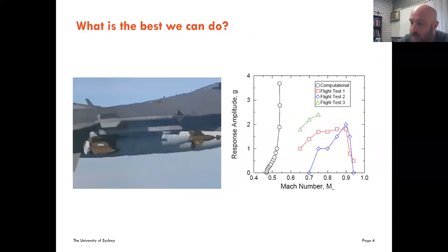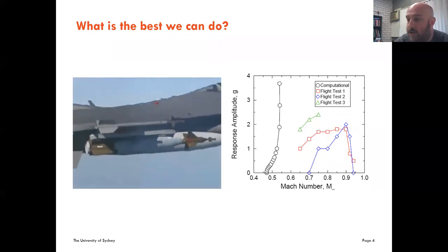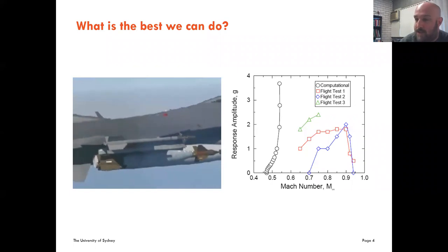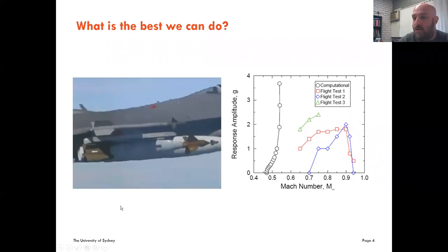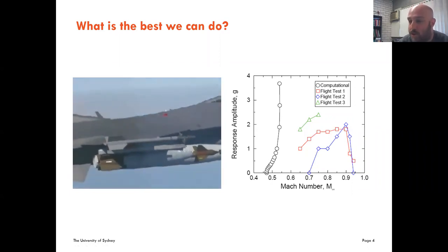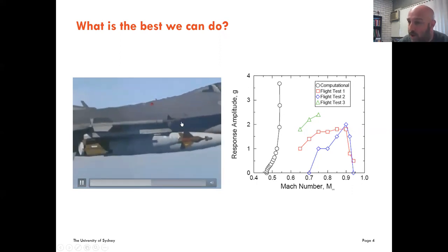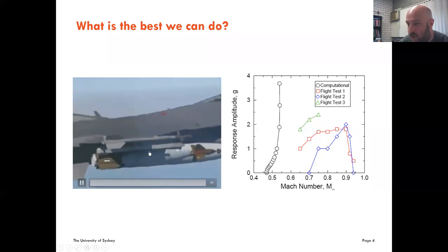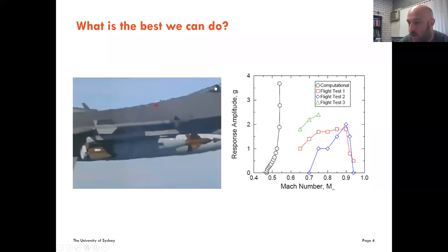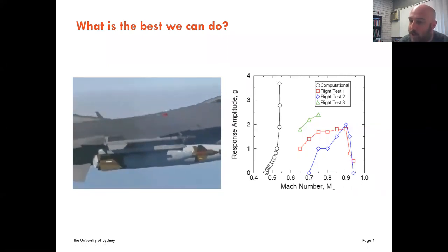And what came further along is this type of problem. This is an F-16, and it's quite common that when you've got a nice slender wing and you put a mass at the tip, it just oscillates away. It becomes completely useless as a military aircraft because you cannot get a lock-in with that missile. It's also extremely uncomfortable for the pilot. If you were to see the video, looking at the pilot, his head is actually shaking from side to side against the canopy.